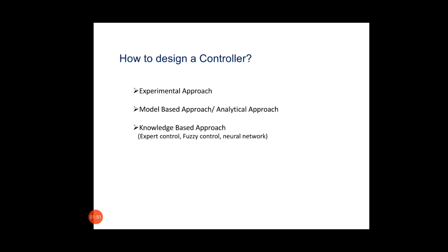It is a highly nonlinear process model, and therefore instead of relying on quantitative information about the process, we rely on the experimental knowledge about the process, about the operator's experience about the process, install a controller and tune the parameters of the controller so that an effective tie-up between the control variable and the command signal is achieved.